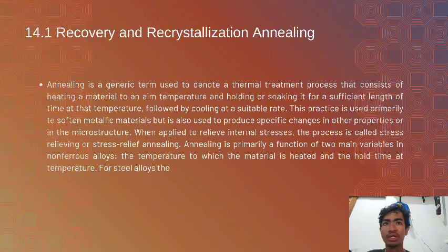For steel alloy, the rate at which the alloy is cooled back down from the soak temperature is a critically important factor during the annealing cycle, and this cooling rate may also be an important factor for specific non-ferrous alloy. When annealing is performed for a short period of time or at low temperature, the hardness of cold worked alloy remains relatively constant. This is true because the level of temperature activation is not sufficient to significantly affect hardness during recovery. There is some movement and readjustment of dislocations during the recovery stage, so some properties do change during recovery annealing.